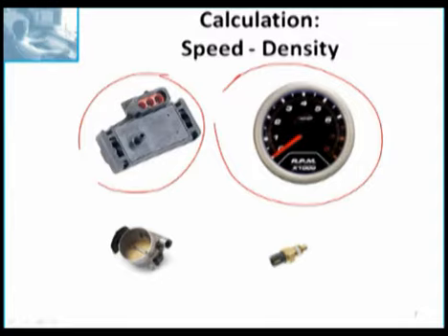If the MAP sensor is unresponsive, fuel trim could be lean off idle. So what I'm talking about is a MAP sensor that doesn't change when you open the throttle. That's fairly easy to check by looking at scan data. What's hard to check is to see if a MAP is out of calibration. If a MAP is out of calibration, fuel trim could be lean under all conditions.